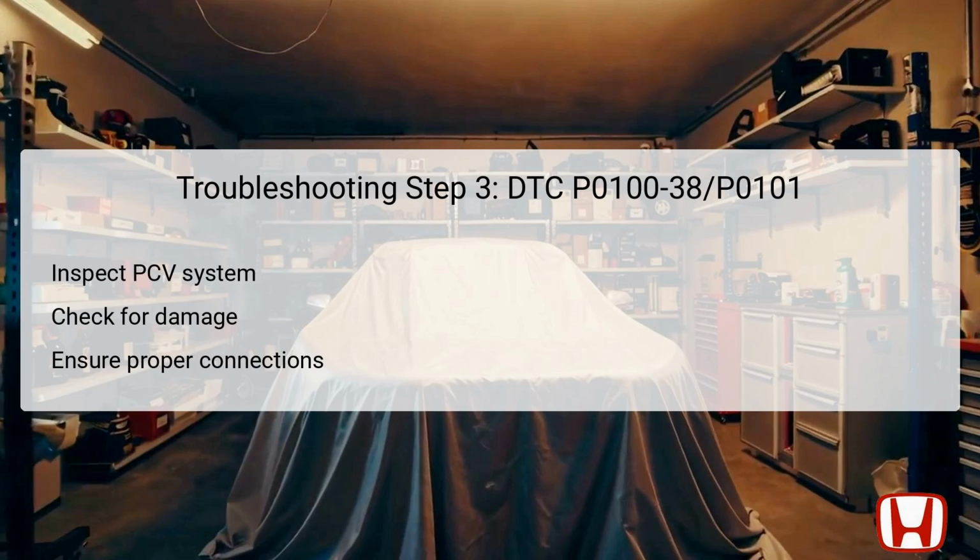Use a visual inspection protocol to also check that all parts, especially those between the turbocharger joint to the throttle body, are in good condition. If any anomalies are found, repairs or replacements may be necessary to ensure optimal functionality of the intake air system, which directly influences the MAF readings.